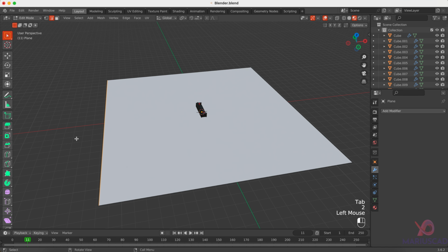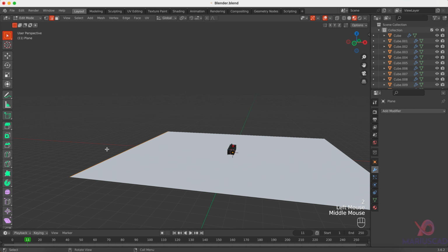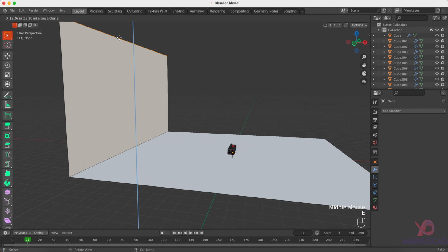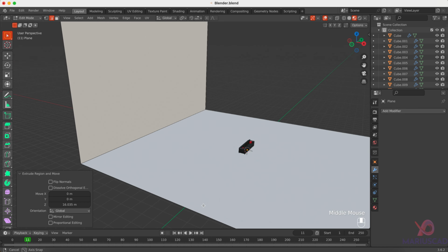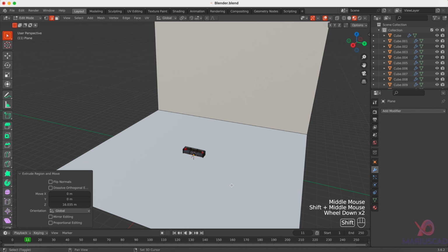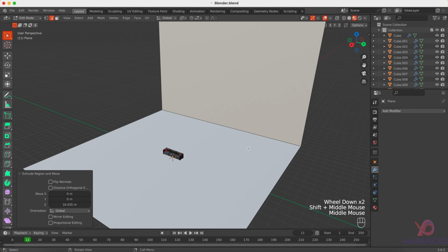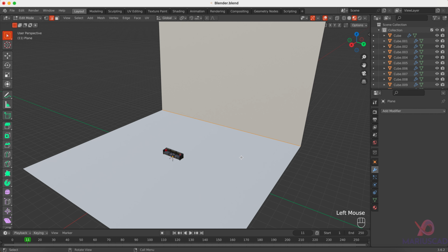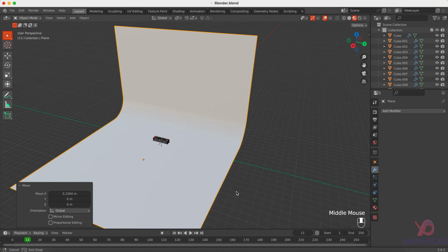I will go in the edit mode, I will press 2, I will select that edge and I will extrude it. Good, and that one, that edge, Control B to bevel it. Okay, I will add many segments. Okay, like this, and after that I will shade smooth. Okay, even though I can move it, let's say here is fine.